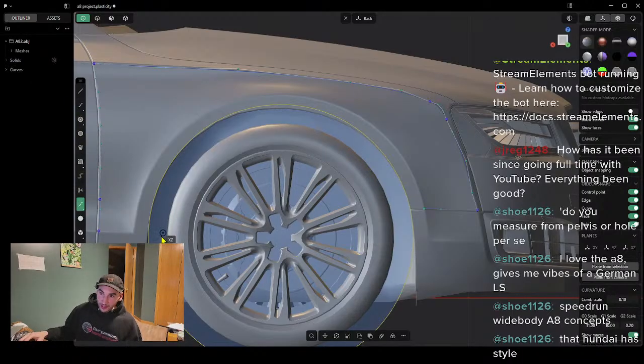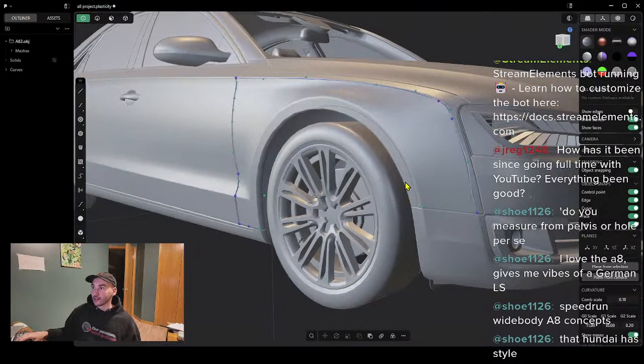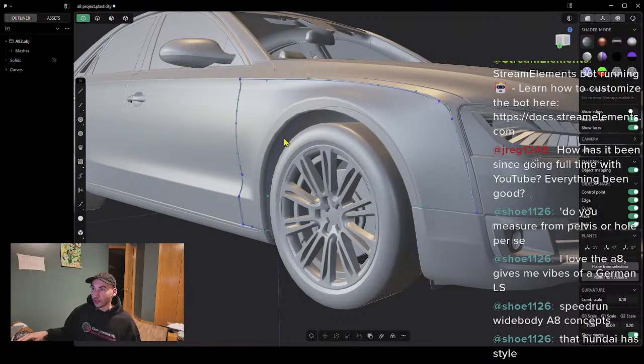We'll go ahead and do a split here. Boop. And we'll do another split here. Boop. And then we'll trim off the excess like so. All right, so now we got our curve here. It's inset a little bit, so we're gonna have to move that on out. So go ahead, edge tool select, hit the curve, G to move it out, and move it along the x-axis